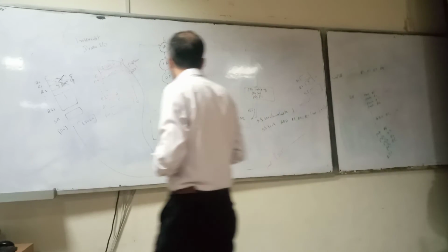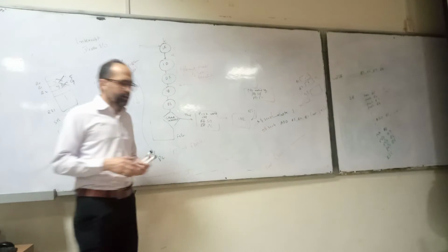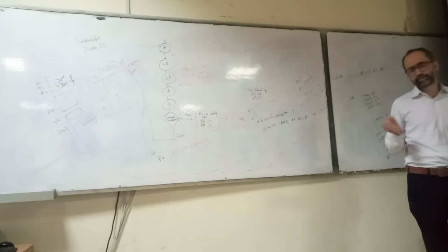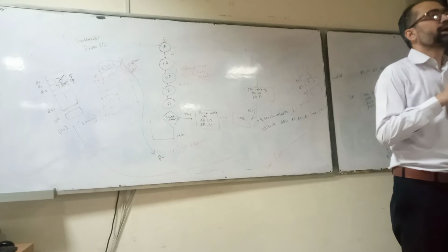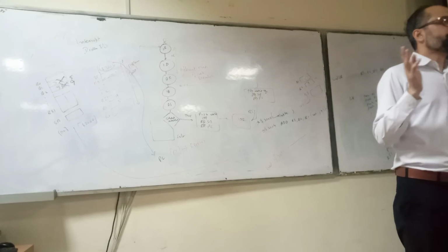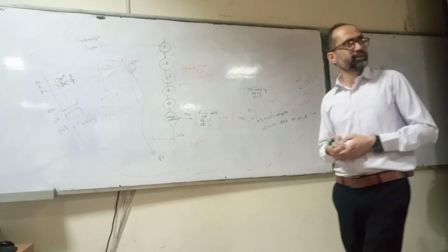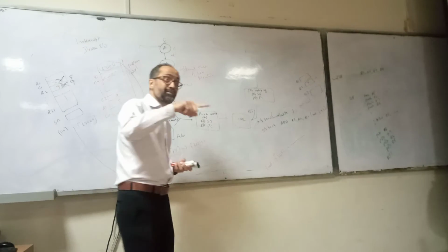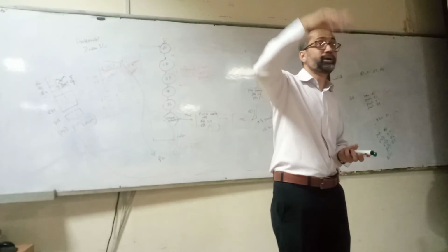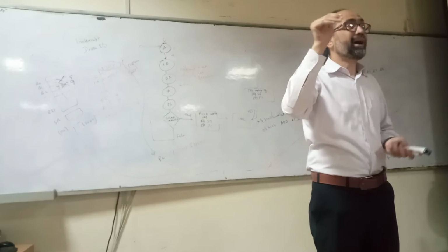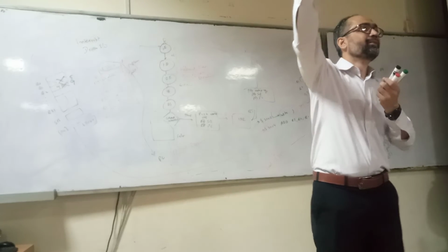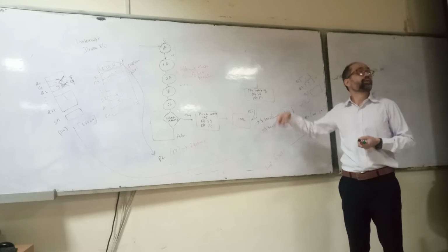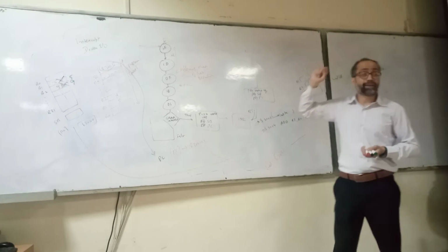Okay, now we have studied that whenever a microprocessor is executing a program and an interrupt arises, because an interrupt is asynchronous, it can arrive at any time. So the microprocessor will first complete the current instruction. Okay. And then it will determine the next address. The next instruction to be executed can be the next sequential address, or it can be a forward address. Okay, the forward address can be a forward jump or backward. It depends on when the microprocessor is interrupted.